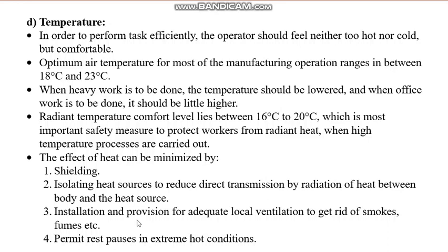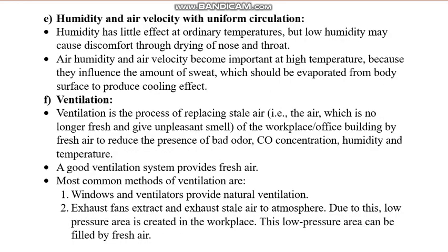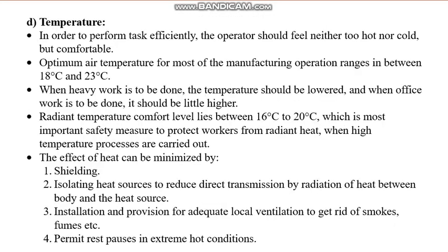Installation and provision of adequate local ventilation to get rid of smokes and fumes can be done. You see, if there is breeze coming from the windows or from the ventilators, at least it will improve the situation there. And permit rest pauses in extreme hot conditions. That means you can give him a little rest for some time, to all the workers you can give. Okay, that is about the temperature.